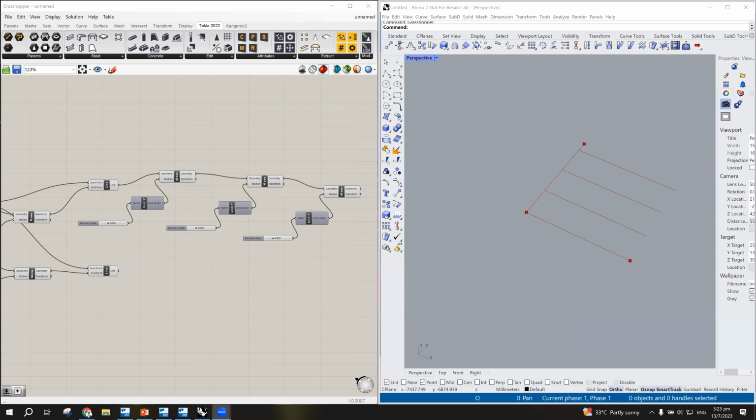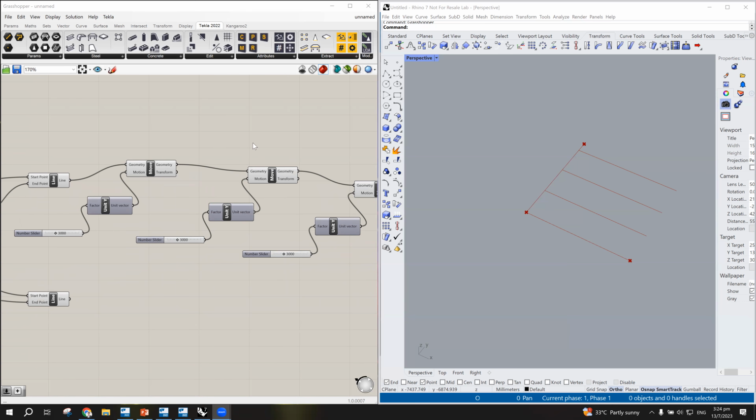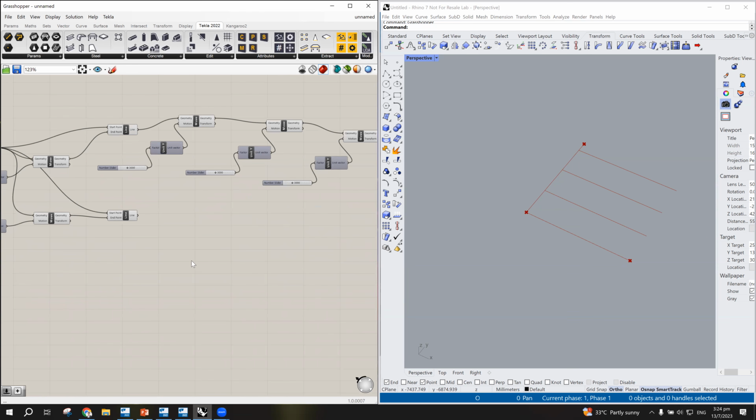All right. So anyway, I can continue because all I have to do is the same thing. I will just repeat the procedure that I have done on the move on the line, on the Y direction. So again, move command. Click on this, and then this time I'll use the X unit X here, and then just double click, and then 3 meters also.